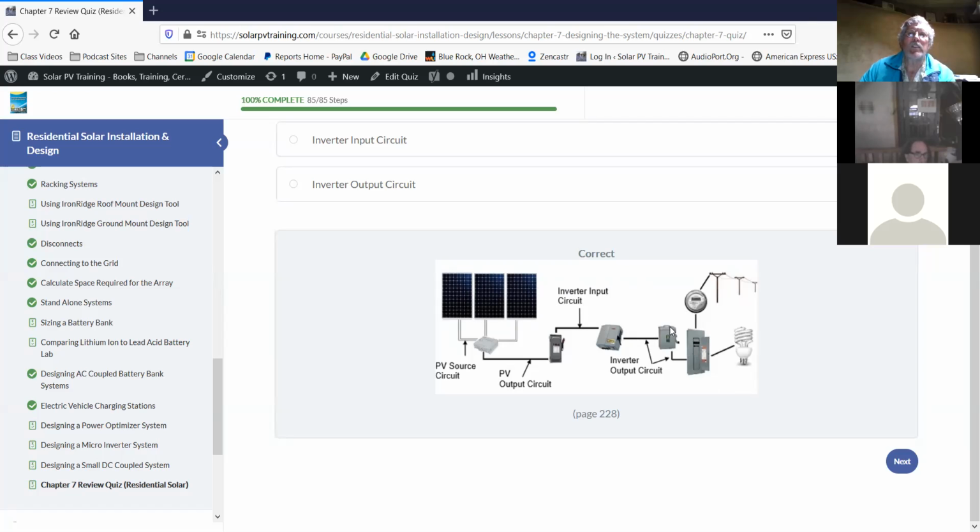And I think the code is slow to adapt because I think what you're getting at is as soon as I would pull the meter, it would lose sight of the grid and the anti-islanding would shut it down. And that's true. So I think that the AC disconnect is just a legacy issue, but it still is the code. Okay. All right.